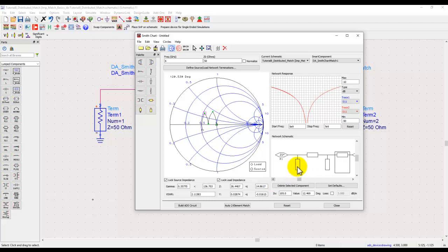The only thing I need to do here is this is not going to work, and I will need to add a series line, and the series line will have this kind of transformation. So I will extend it a little bit, and then I will move my line a little down till I hit this unity point, and now I can add a series line here, and then I can adjust it so that this line crosses the unity point.